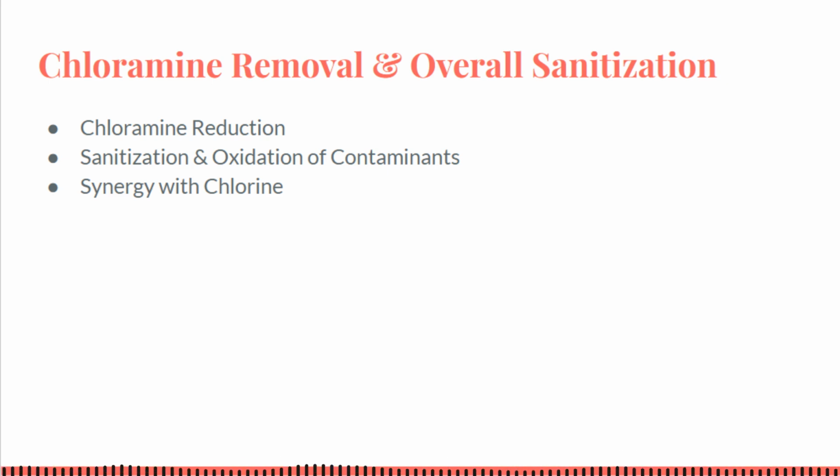AOP's hydroxyl radicals have an even higher oxidation potential, meaning they can inactivate or oxidize 99.99% of pathogens and impurities that flow through the unit. For example, advanced AOP units have been certified to kill 99.9% of bacteria and viruses, including chlorine-resistant parasites like Cryptosporidium when sized properly.